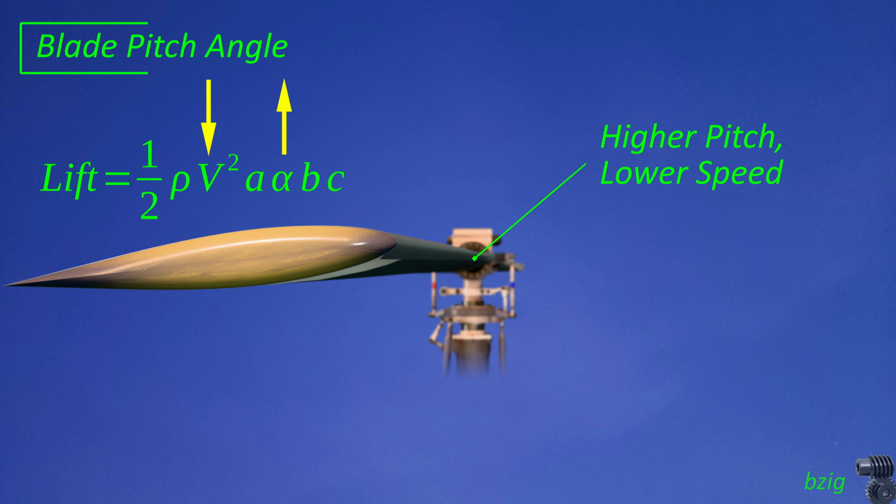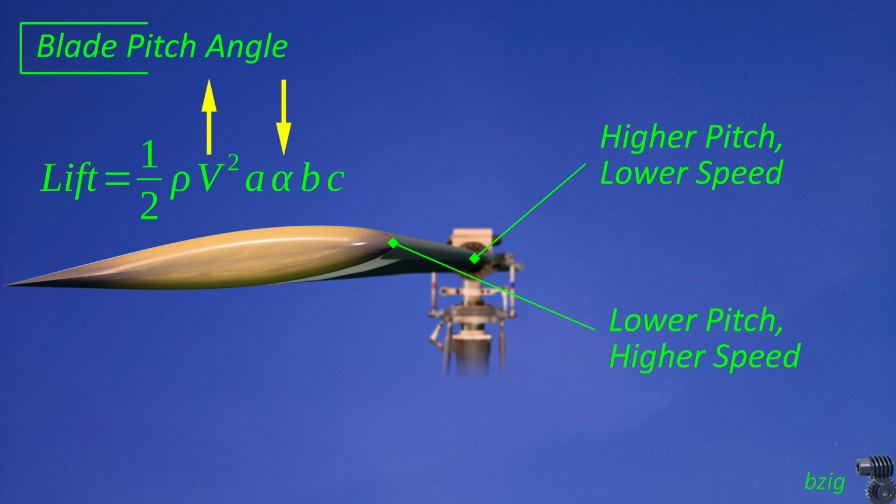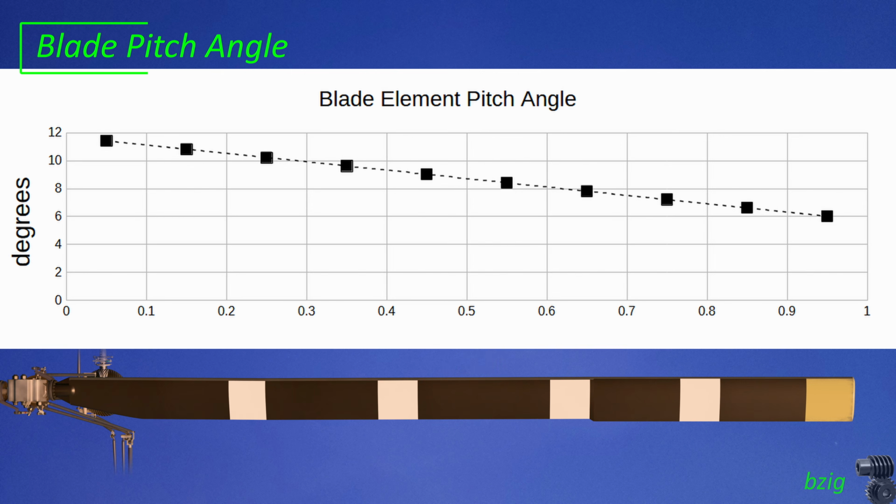Blade twist results in a more even distribution of lift than we'd see if the blades were untwisted, because the lower velocity at the root will have a higher angle of attack, and the higher velocity at the tip will have a lower angle of attack. Like tangential velocity, blade pitch angle is relatively easy to calculate. It only requires knowledge of the blade's geometry and the flight control rigging.